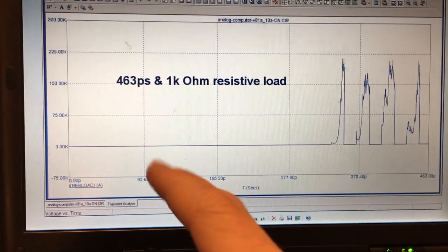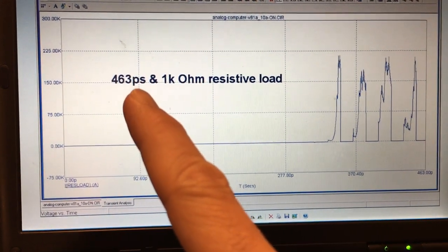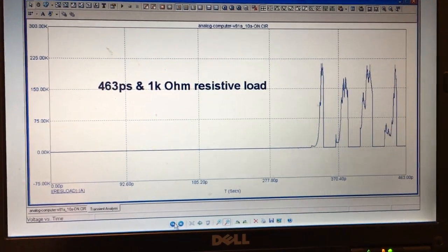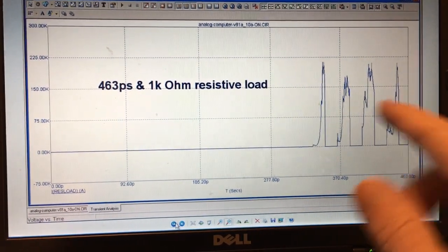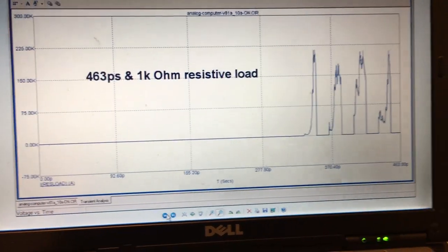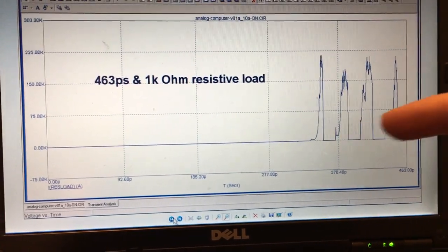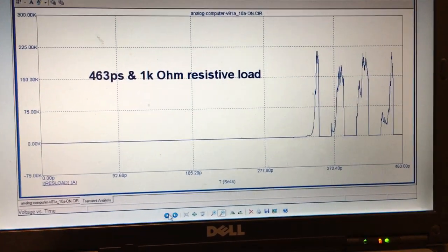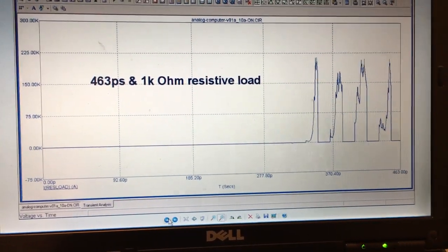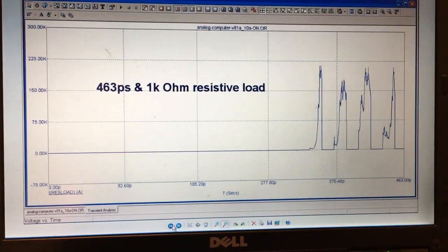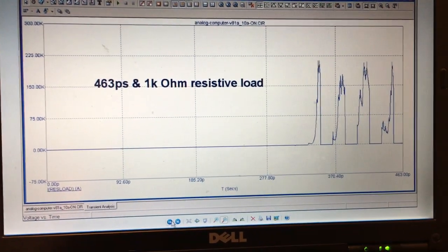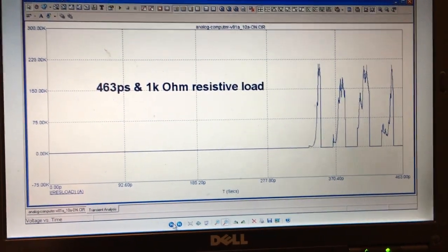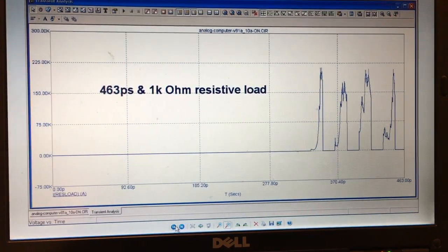So I found I could increase my range to 463 picoseconds. If I go any higher, I get matrix is singular error, and that tells me that the next group of spikes, you see, the reason why the node voltages were higher than normal is because it's getting ready for a big, massive lurch of a spike greater than before. That's usually what happens with this thing. So it's warning you. So I couldn't go to 464 picoseconds because the simulator maxed out at matrix is singular,